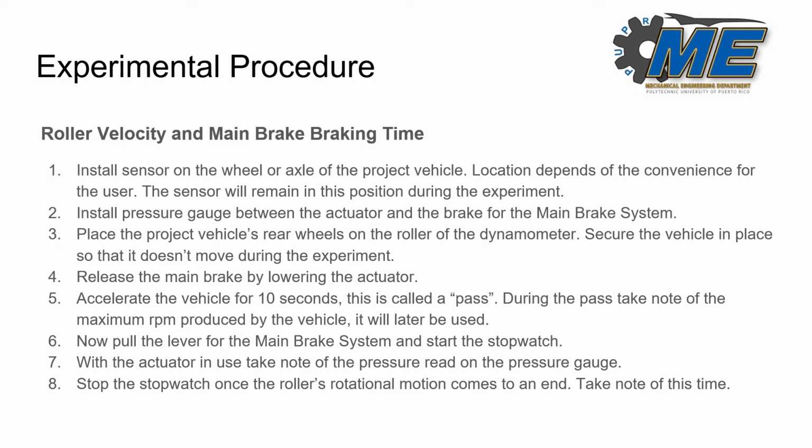We need to place the project vehicle's rear wheels on the roller for the dynamometer. We have to secure the vehicle in place so that it doesn't move during the experiment. Release the main brake system by lowering the actuator. We have to accelerate the vehicle for 10 seconds.